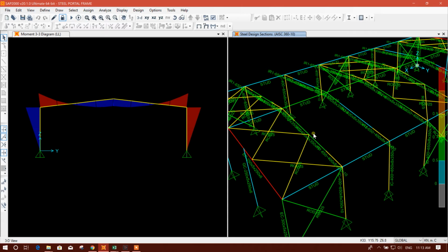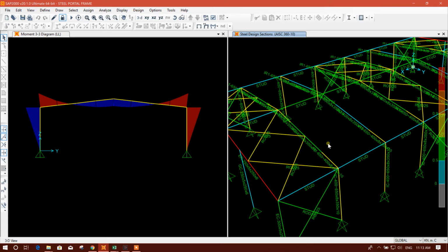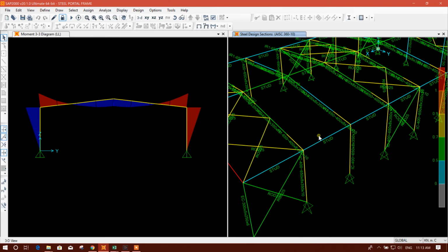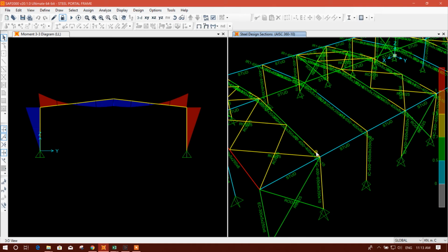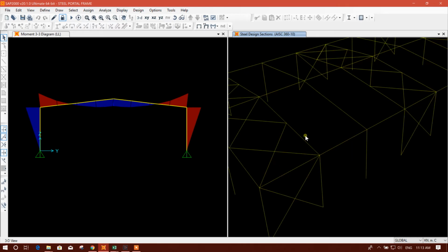Purlin will stay at the top flange of the rafter, and it will also be connected with the bottom flange with a stay angle. Then we can apply this LTB ratio, otherwise we cannot. We can provide only for the top flange. So in that case, in the drawing we have to show the stay angle connected with the purlin and the bottom flange of the rafter.